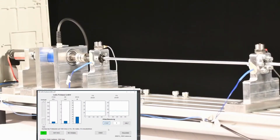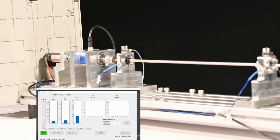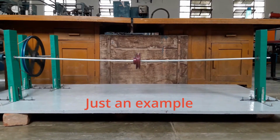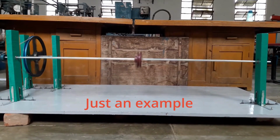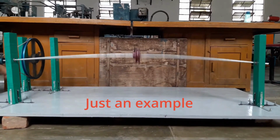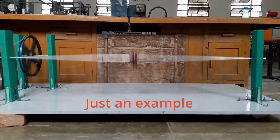So now let's check the critical speed of the selected ball screw with the fixed float bearing arrangement. But what is critical speed? We can say critical speed of a shaft is the speed or range of speed where the rotational speed of the shaft matches the first natural frequency of that shaft. And when the natural frequency matches the rotational speed, there will be a resonance. And due to the resonance, the ball screw can vibrate excessively and it can be bent.